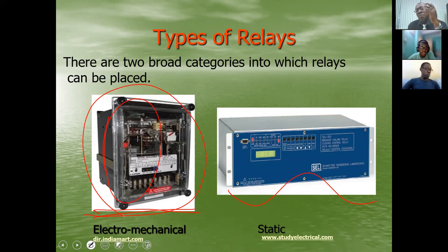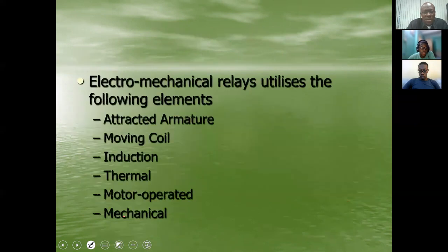You would still have much of the secondary current flowing to the relay, because that resistance on that parallel path is significantly less than the impedance of the core of your current transformer. So that's something we're just reiterating.